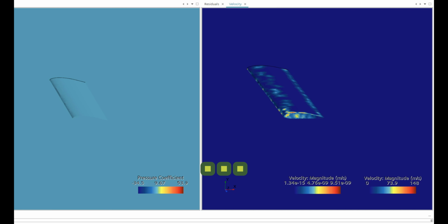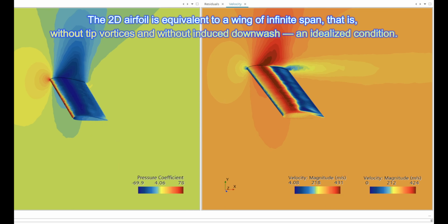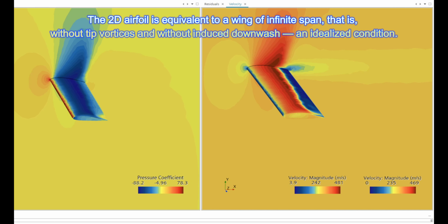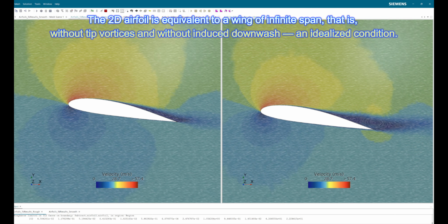So, why do we need fluid structure interaction? In all previous calculations, whether 3D or 2D, we assumed that the wing keeps its geometric shape unchanged during flight, but in reality, the wing, as well as other components, deforms under complex aerodynamic loads. For example, the wing vibrations you see when you're on an airliner are a form of aeroelastic oscillation.